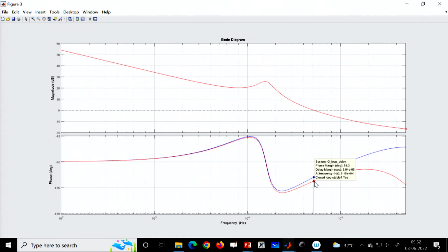Now, here we are not doing any exact pole-zero cancellation, but another interesting point: you see the gain plots of the analog and digital are exactly identical, because I told you the delay will have no contribution in the gain because its magnitude is 1, but it will contribute to the phase, and the phase will deviate drastically as we move further and further, because it is omega into tau d. As omega increases, the phase lag also increases.